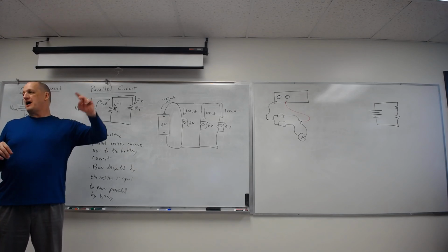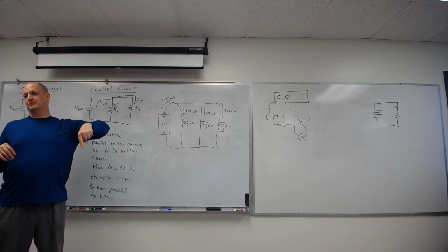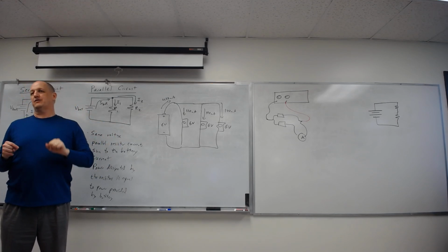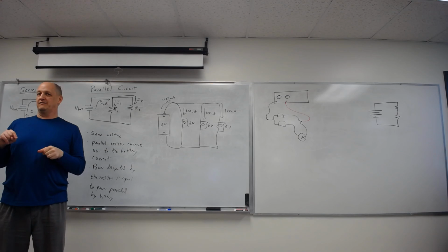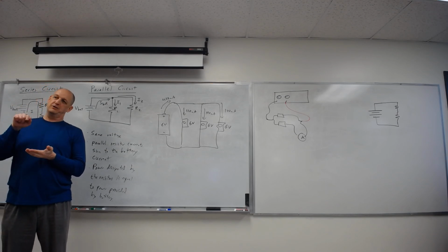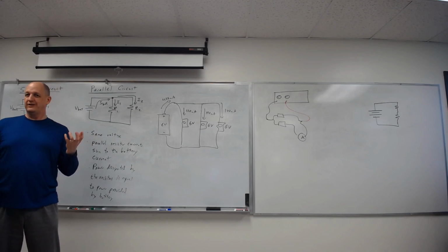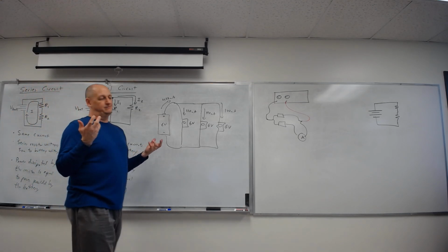A couple other things. A big thing, and I stress this in the homework: do not, under any circumstances, connect the positive of the battery to the negative, or the positive of my power supply to the negative, because you're asking for infinite current, which is going to blow the fuse in my ammeter if we're lucky. I have a couple ammeters that are burned out because people did that and just fried them. Don't do that.